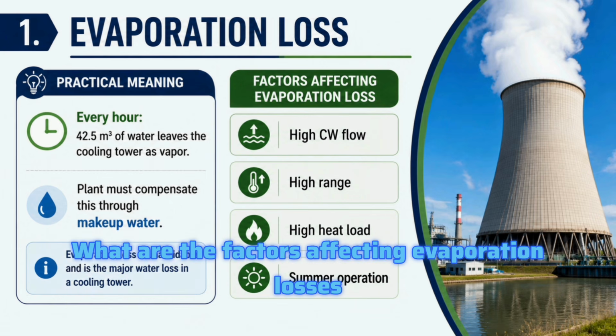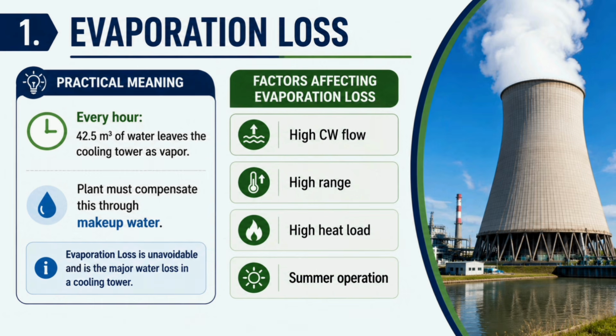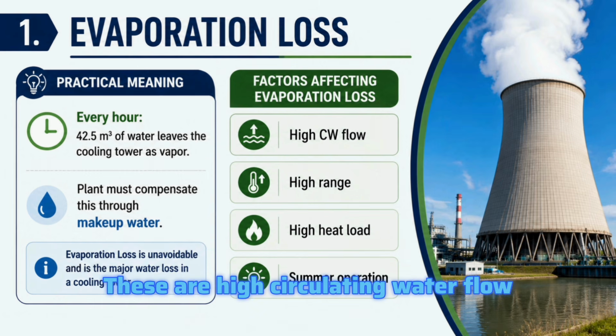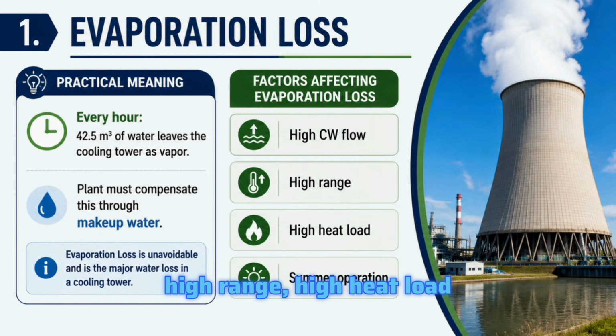What are the factors affecting evaporation losses? These are high circulating water flow, high range, high heat load, and summer operation. These are the reasons which increase evaporation losses.